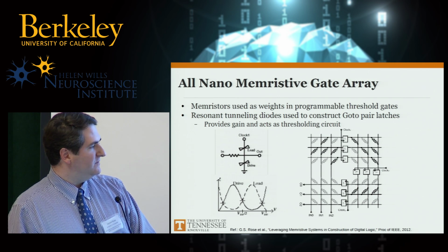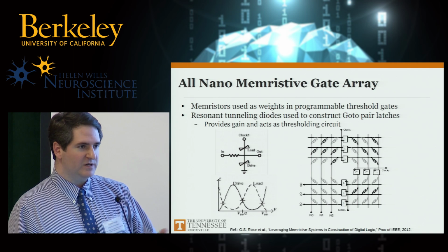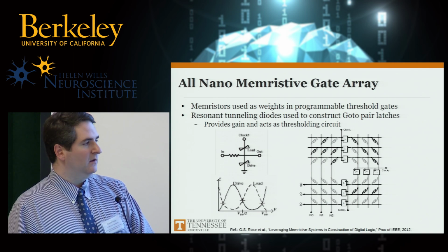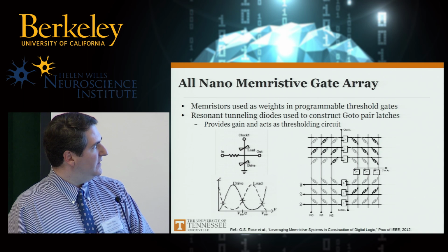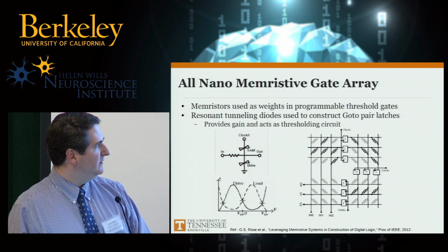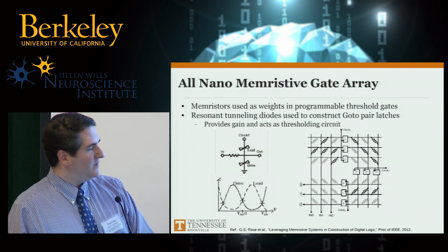One thing to note is that if it's a diode, this peak to valley current ratio is dictating your threshold essentially. So the diode itself might be somewhat fixed. However, there are other devices based on the same property, essentially a resonant tunneling transistor, where we can modulate the size of that peak. So we can modulate the threshold as well. That might be interesting.